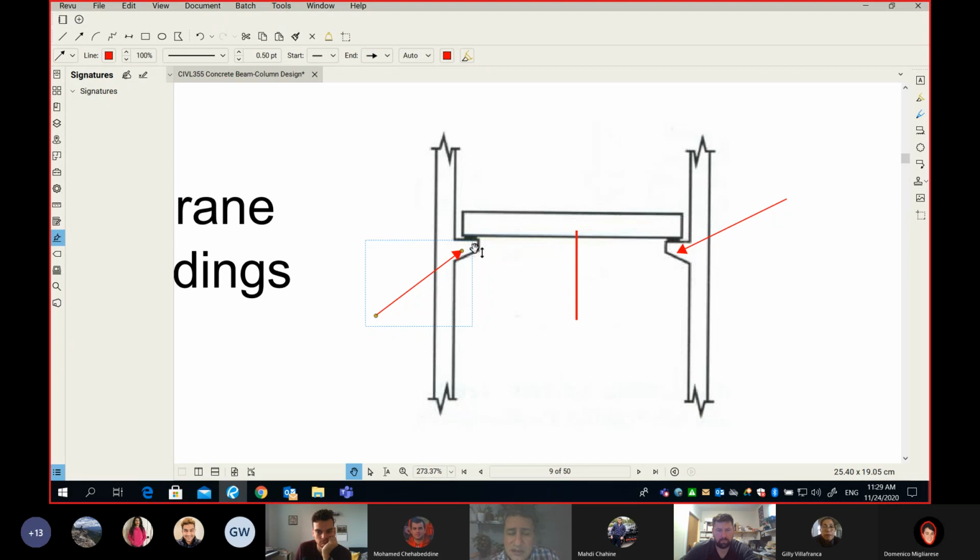And you can tell this cantilever will simply bend your column. Here is the load, the reaction from the crane, and here is the centroid of your column, and you can tell there is an e in between them. There is eccentricity between the centroid of your column and where you apply the load. Here is your e, here is the eccentricity.